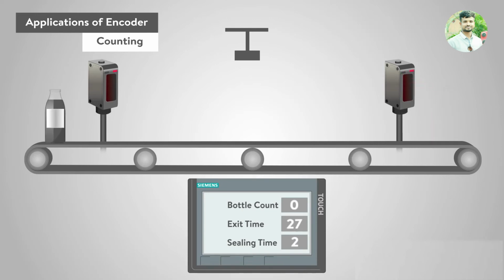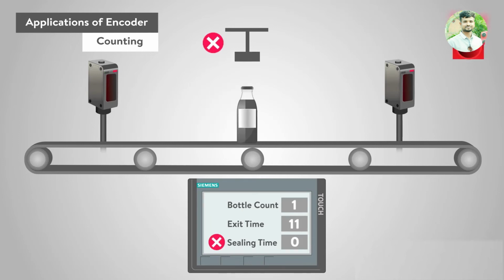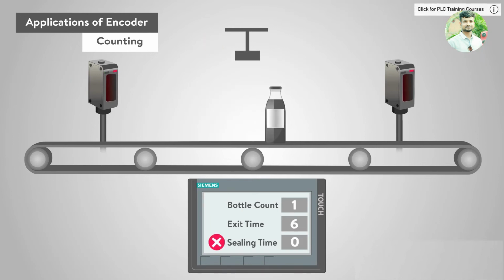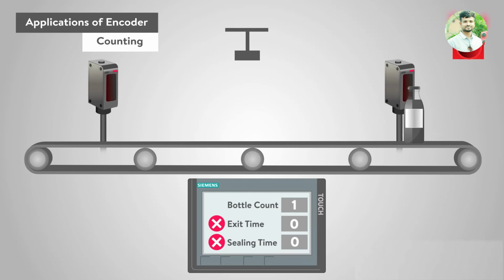Some of the requirements for this station are that the same number of bottles that enter the assembly must exit in a predetermined time frame. The bottle must not remain in front of an entrance or exit sensor. The bottle must not be exposed to the inductive sealer longer than a predetermined amount of time. You must make this assembly flexible enough to handle many types of bottles and entrance and exit sensor placement.